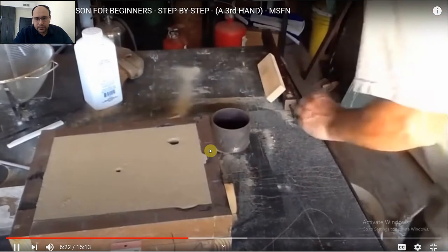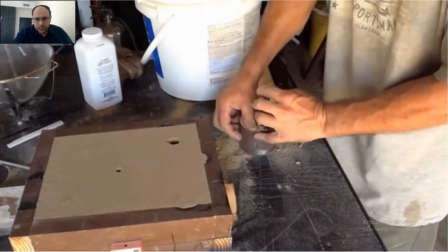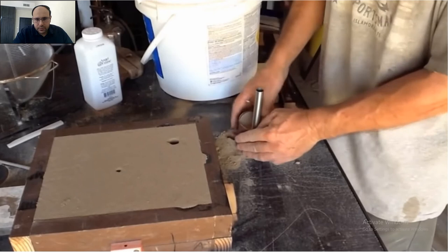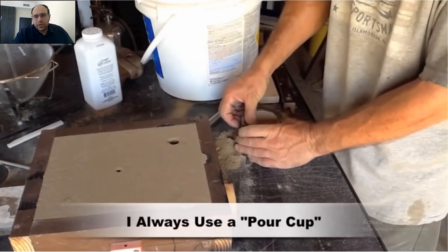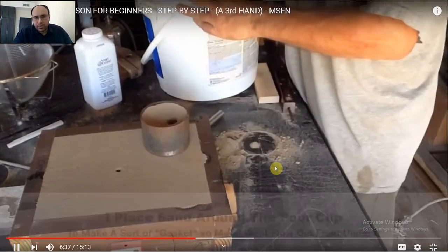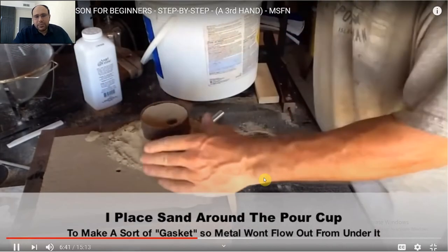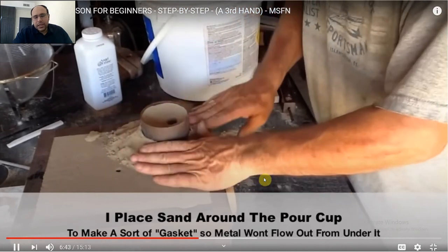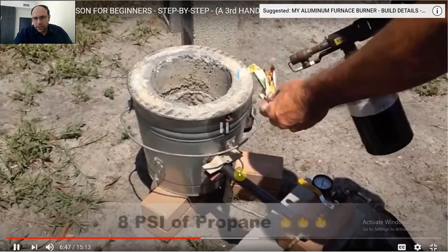Back onto the drag. I'm gonna prepare a little pour cup to give me a larger target to hit when I'm pouring the metal. And here, this is ready to cast some metal. He's doing a pouring cup like the furnace on the top here. As he just mentioned, it would be difficult for him to target the very small opening of the sprue to fill the mold cavity.